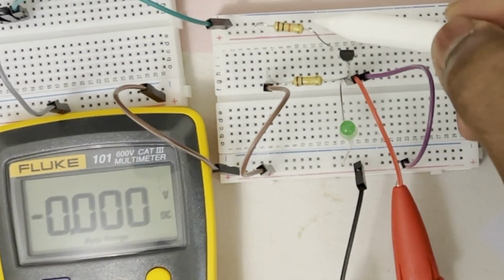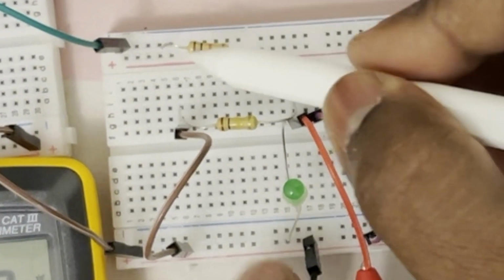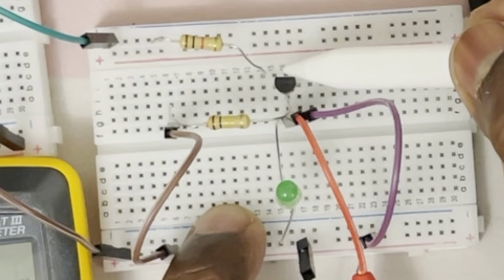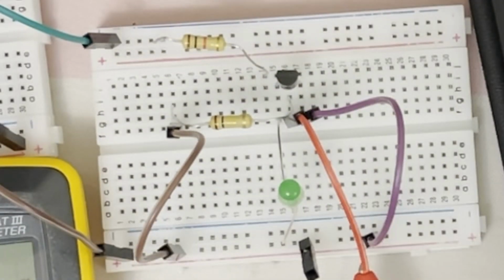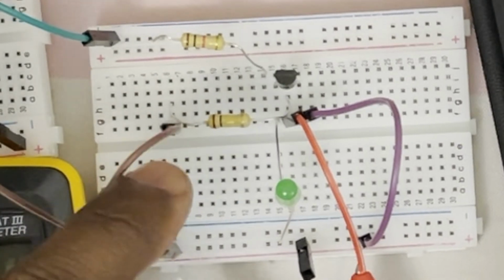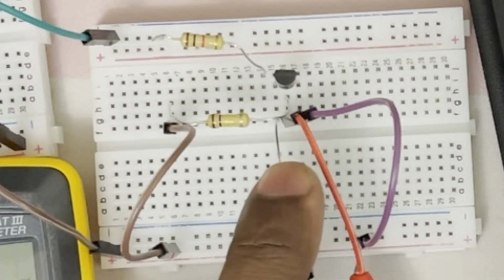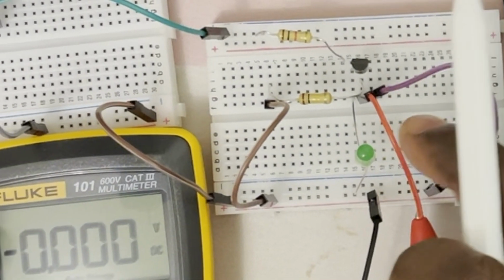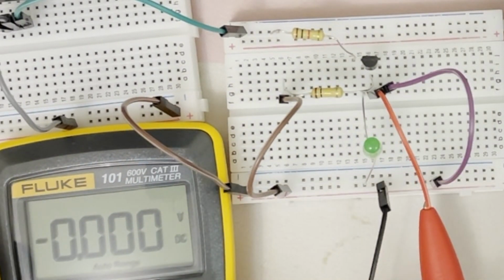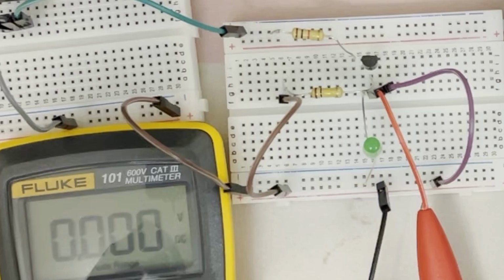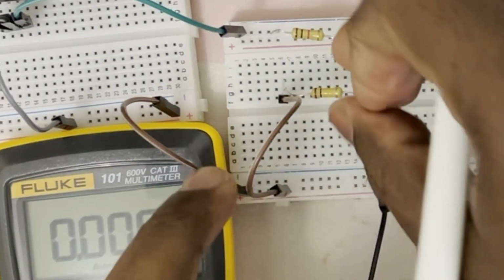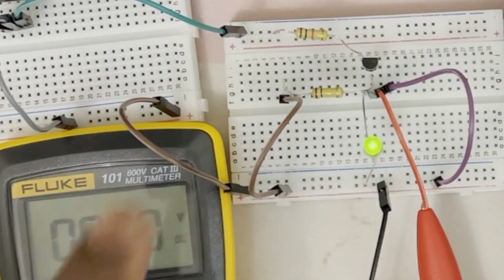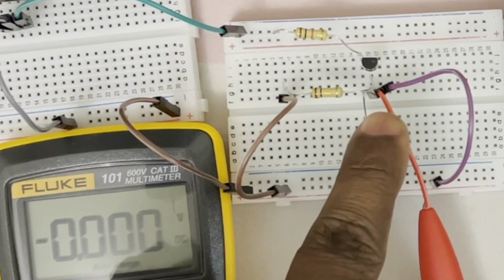Why? There is a mistake. This resistance should be connected from the source to the collector, but you can see here the collector and the resistance are not connected together, right? That's why though you give 0 input to the base, LED is not turned on, right? And also you can see the base to emitter voltage VB is 0 volt. That means transistor is not getting any input from the source. Okay, how to make this okay? Just put it like this. You can see input is 0, output is 1, right?